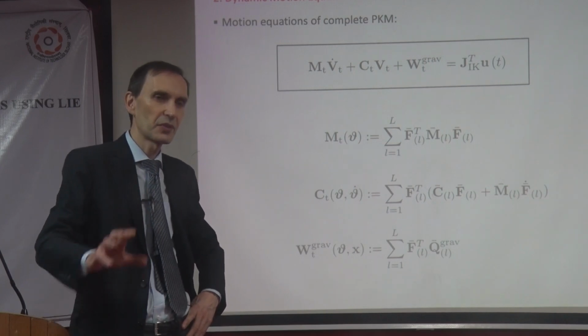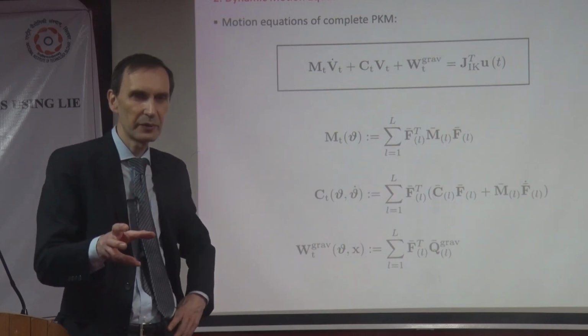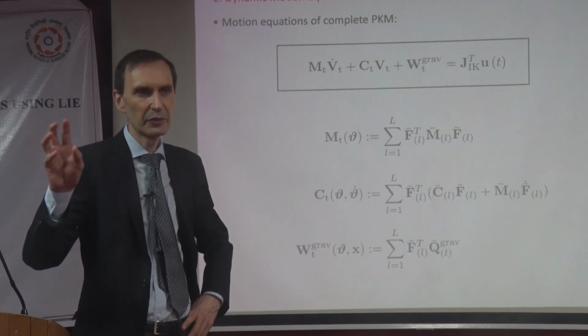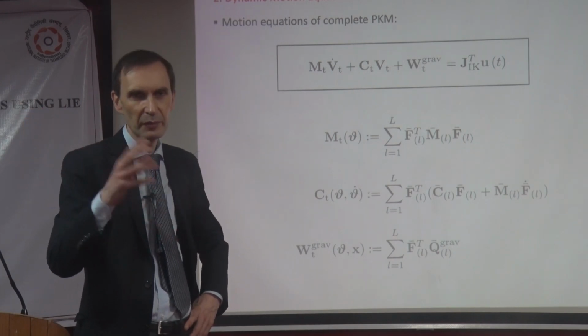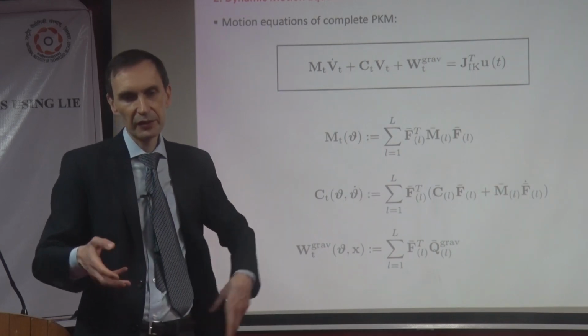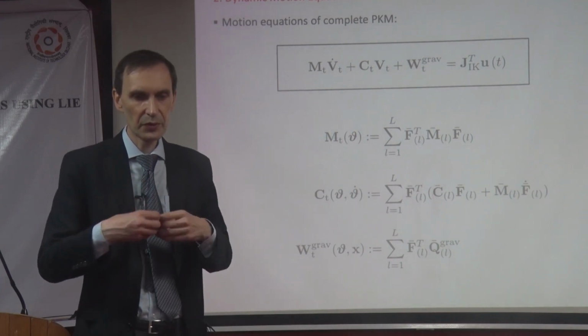Okay, so now the question was about an underwater vehicle. So you have a moving platform, and you have a robotic arm on top of it. For the robotic arm, you could use what we used before, like the PID controller, with the non-linear feed-forward maybe. And then on top of it, or before, depending on how you call it, you should control the platform.